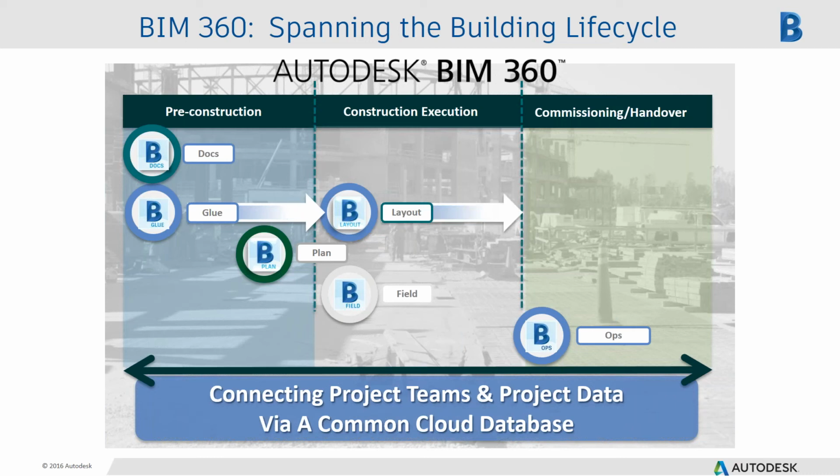Then we have BIM 360 Layout. BIM 360 Layout utilizes all of the points that are put into the model via Autodesk Point Layout. So Autodesk Point Layout puts the points into the design file. BIM 360 Layout allows us to utilize those points in the field.